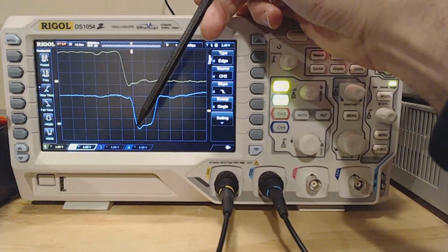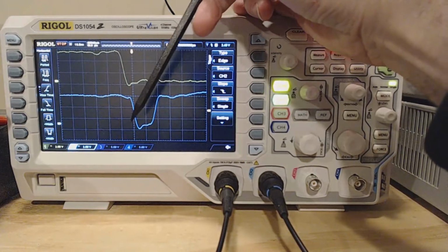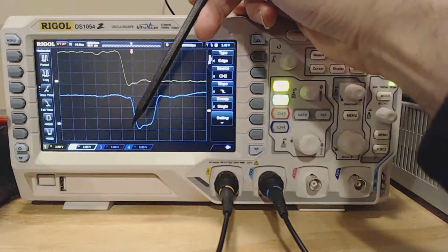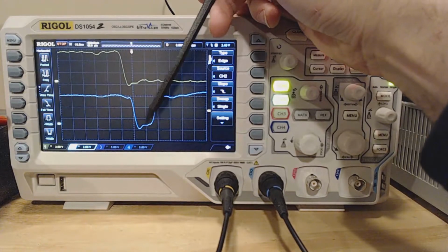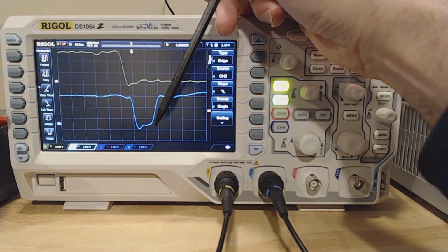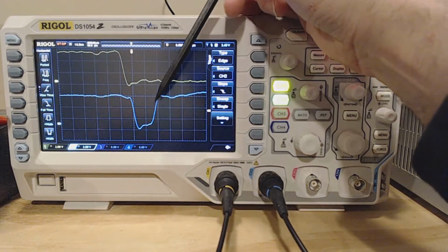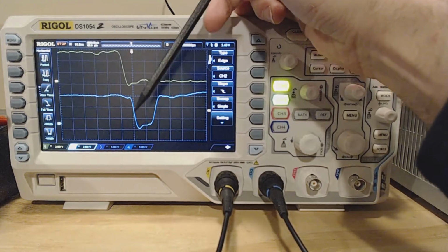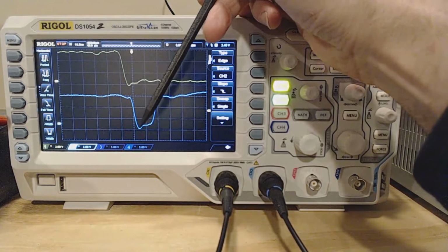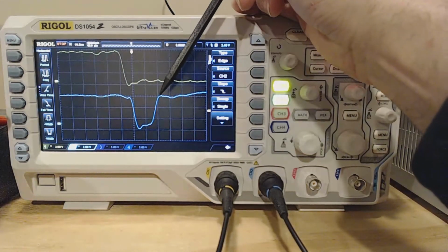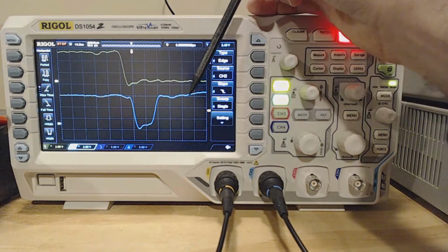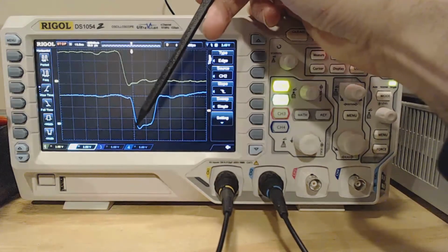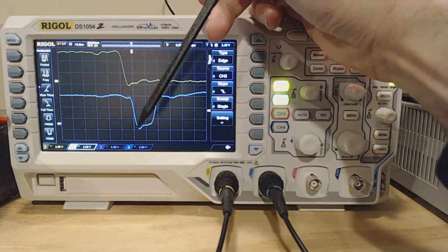And the reason that the other input of the OR gate doesn't change immediately is because that has to propagate through those 3 inverters, and that takes time. Each of these grid squares is 10 nanoseconds. So it looks like there's about 15 nanoseconds worth of delay between the time when the output of the OR gate goes low and when the output of the OR gate goes high again. Essentially what has happened here is eventually the low input of A propagates through those 3 inverters and produces a high signal, sending the output of the OR gate high again. So yes, this is our glitch. Our output, which was never supposed to be low, was in fact low.